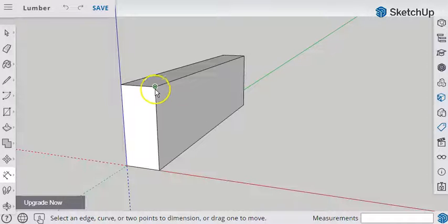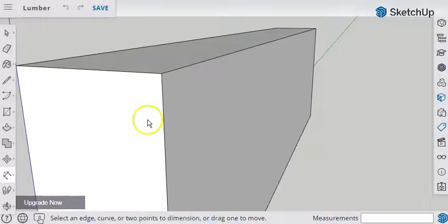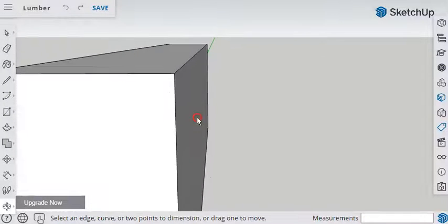But if you wanted to round it off, and I'll undo this in a moment, you basically unextrude. I'm zooming into this spot, and I'm going to hold down the wheel and navigate over. So basically what we would want to do is chop off a little bit of this if you want a true cut 2x4. So what I'd probably do is make a copy of it to do a rounded 2x4.